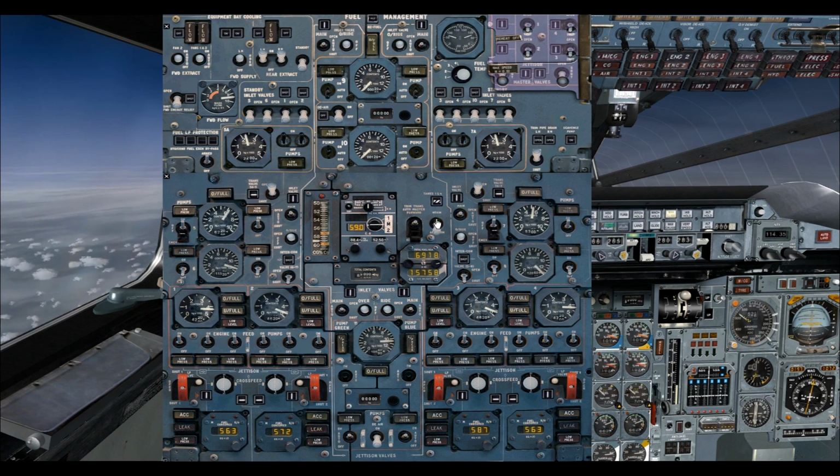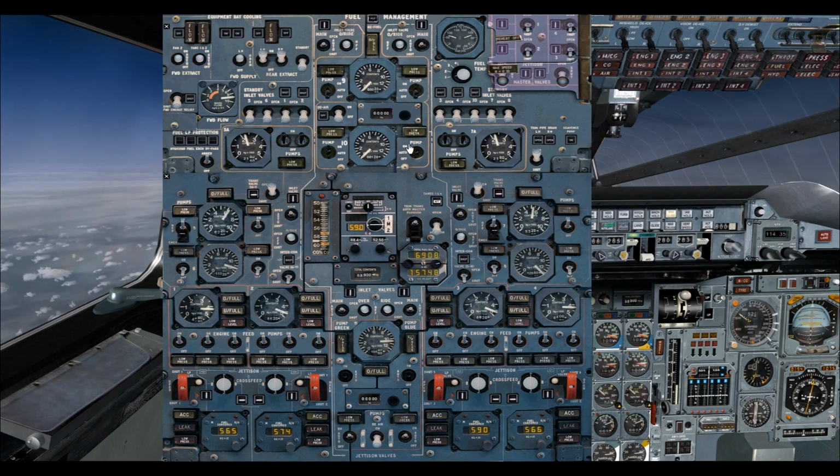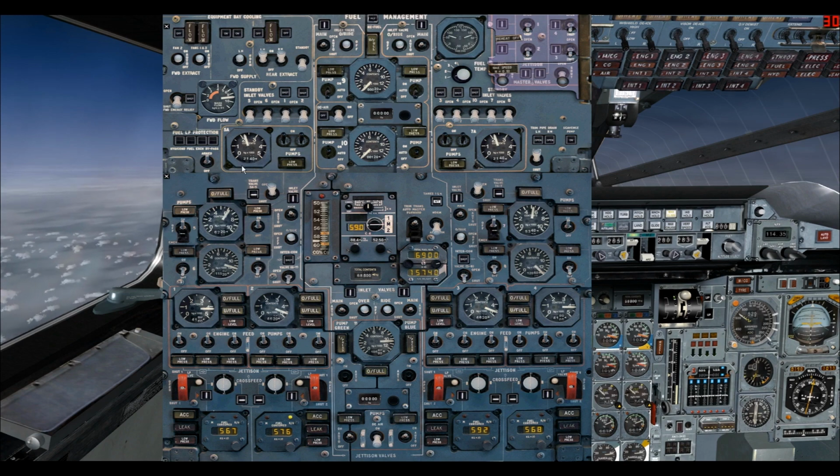Now you recall that tanks 1 and 4 are actually located further up on the aircraft, and these wingtips are actually located further back on the wings. So what's going to happen is tanks 1 and 4 will actually start emptying out down to 2,000 kilos as tanks 5A and 7A begin to empty, and it'll keep our CG stable at 59%.